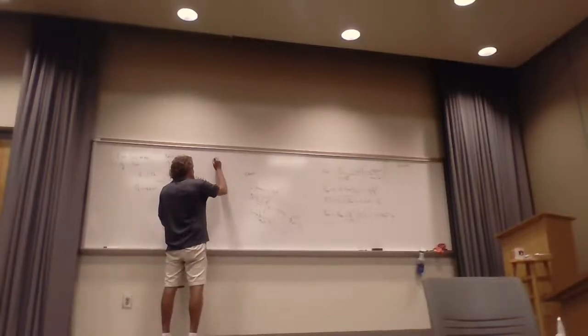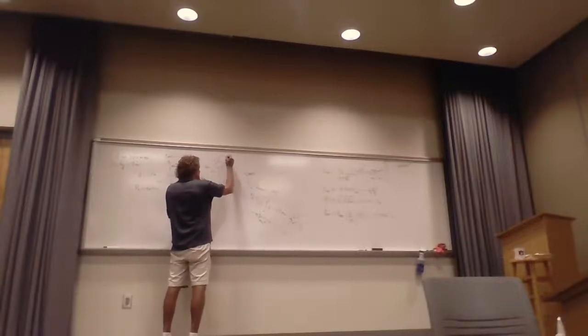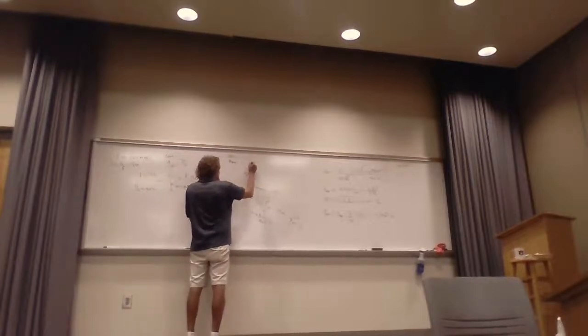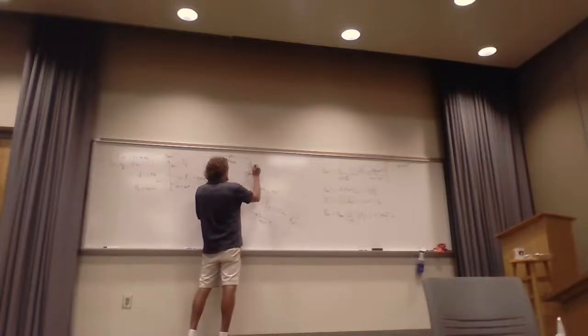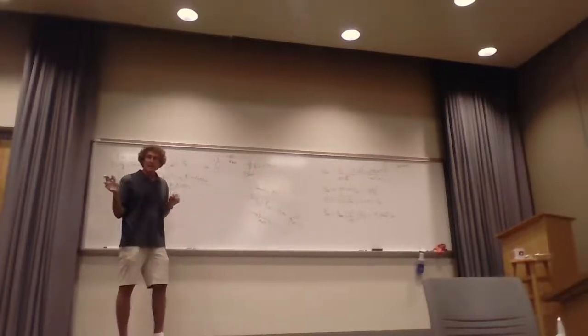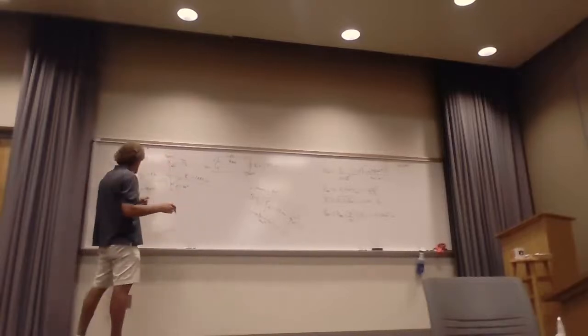So what I'm going to do is draw the equivalent circuit for that. And that means I have an open circuit voltage that I'm going to calculate in a second. Then I have to put the antenna impedance. I only said use the antenna resistance. So now we've got to calculate R rad for this. And then you put down the actual resistance I used, and I used a resistance for the load equal to 1.97 ohms. I think it's that, right? Yeah. So I gotta calculate R rad for that.